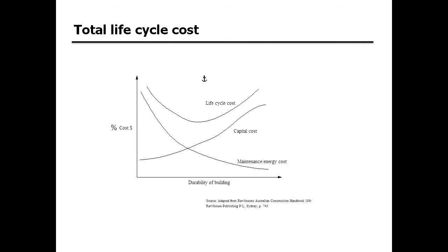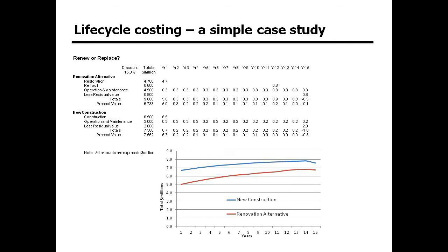To further emphasise the impact of the total life costs, a good example often used is hospitals, where the operation phase, when it's fully costed out for a hospital, typically has operating costs over 2.4 to 2.5 years, which is equal to the total acquisition and construction phase of the building. So that clearly demonstrates how important understanding the costs in use and those life cycle costs are when it comes to establishing a new building.